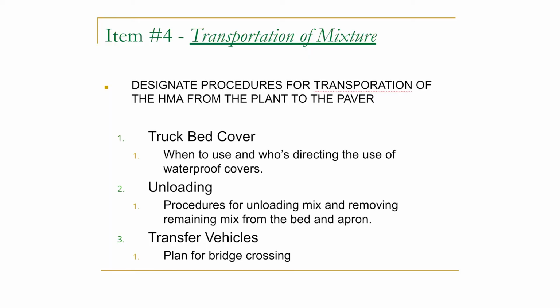So, you did your process balance. Now you've also got to talk about the transportation of the mix to the job. Truck bed covers. When are you going to use them? Who's going to determine when you use them? You got to spell that out. Is there a certain temperature that you're going to start tarping over the sides? You can spell all that out in the quality control plan.